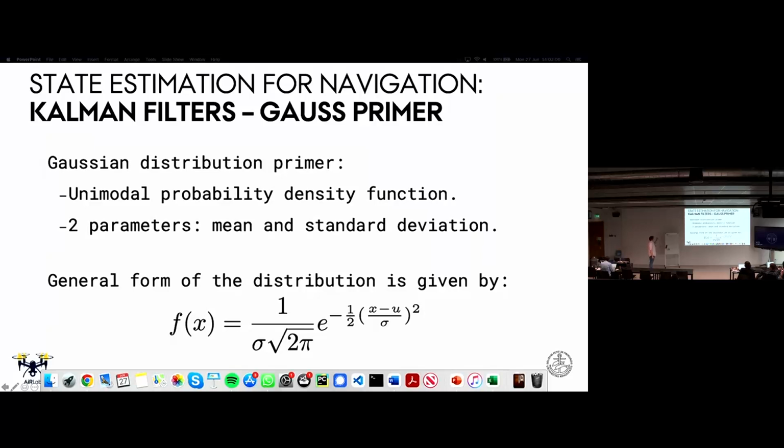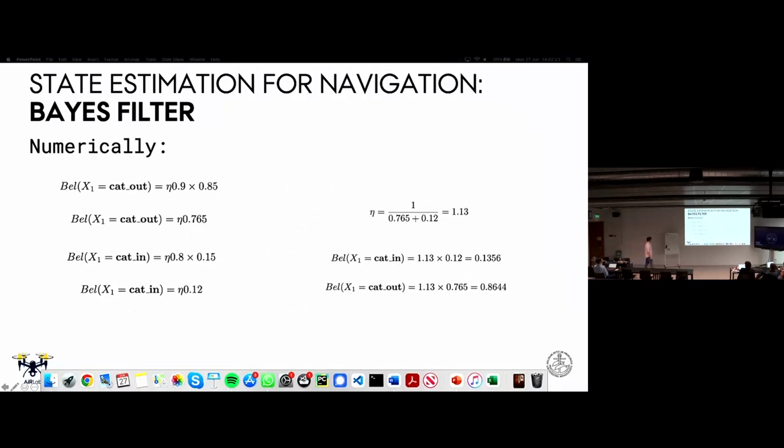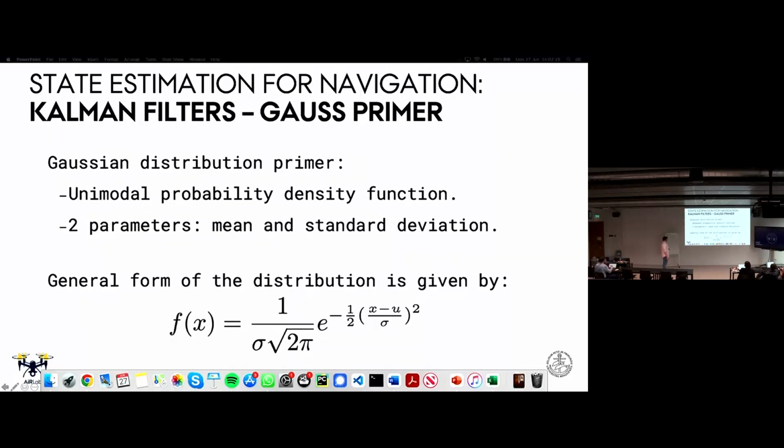Cool. So I'm going to go on to Kalman filters now. Are there any questions about Bayes filters? Or the stupid example. So this normalization constant, do we have to maintain it, or can I just ignore it? It's going to recalculate itself at each step. We just need the relative values. Yep, that's right. I would just forget the data. You could, yeah. But obviously it bounds it nicely between 0 and 1 if you want to do that.